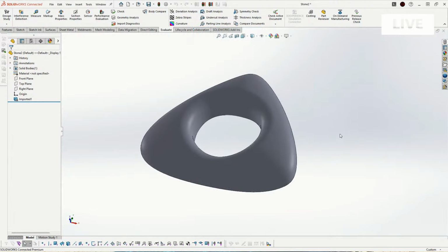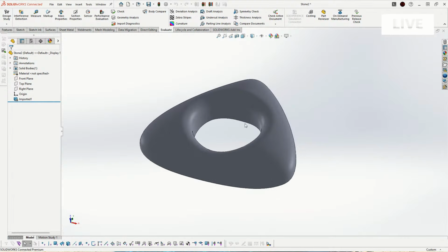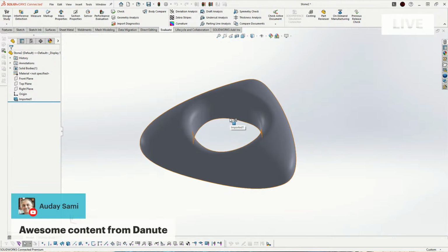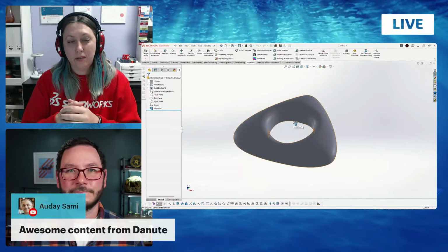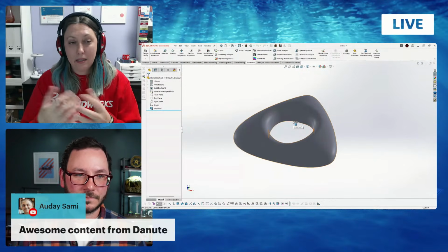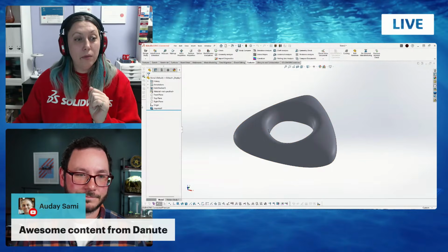Yep, but not the graphics body, right? I see. So we've just got the one, so it just skips right to the end of that process, I guess. Exactly. This is now an editable object, but there is something very, very important. With the standard import that you have, not the solid body with the triangles, of course, because solid body is creating a solid body. It's not imported mesh. In the case of imported solid body or imported surface, without the option that I just checked, it's going inside as a solid. But in this case, you have imported mesh body.